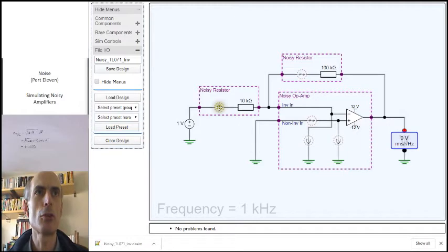The other major contribution is this one here, the source resistor. That's producing 126 nanovolts in the output. Output feedback resistor here, that's only producing 40 nanovolts, despite the fact that this is a larger resistor and therefore has a larger associated noise voltage with it.